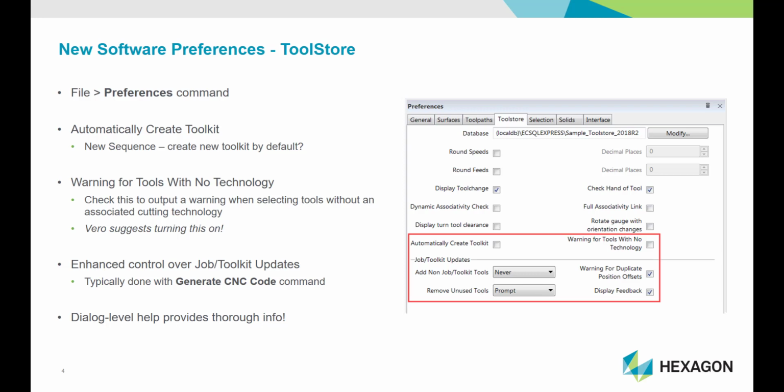That's done in the technology assistant, and it allows the software to look up speed and feed data for your program. So you choose a material, it can then go select tools based on ability to cut that material and return feed and speed calculations that are the values you want to use. It is a great way to streamline Edgecam and have it produce the program quality that you want to and ensure consistency across a programming team.